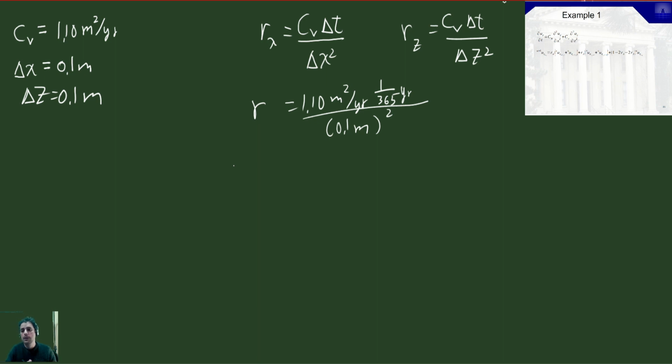This is still a good guide to know if your time step is too large for the spatial resolution that you have. What you gain in spatial resolution, you now have to spend in more time steps. So we're going to get to 10,000 iterations in this particular case instead of the 5,000 that we had to use before, just because of this.